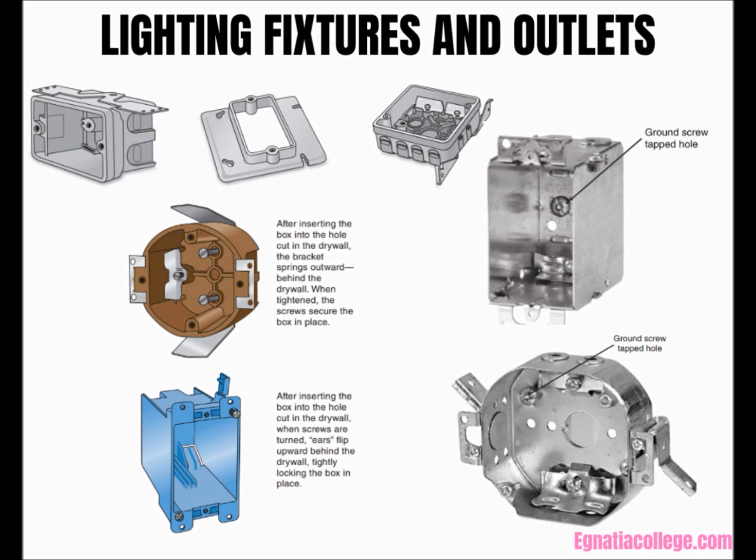Unless the box, device plaster ring, or carton is marked to indicate that it has been listed by the CSA for the support of fixtures, do not use where fixtures are to be hung. Refer to Rule 12-1110. Be careful when installing a ceiling outlet box for the purpose of supporting a fan. See Unit 11 for a detailed discussion of paddle fans and their installation.